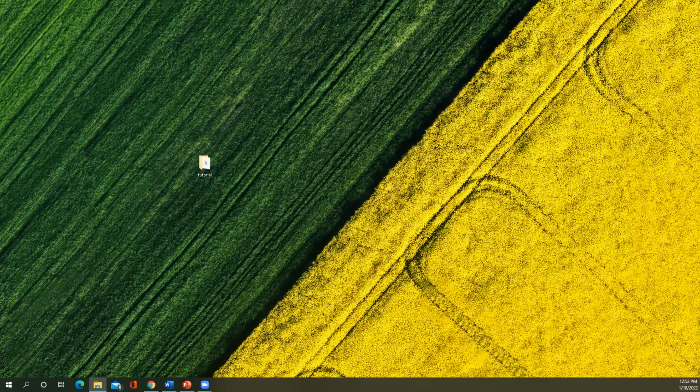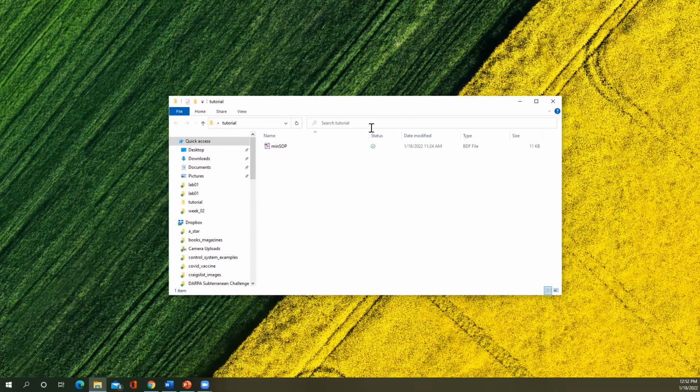Within that folder, when we open that up, I have a Quartus schematic, right? You'll want to do the same in your lab. I believe the schematic you're given is called circuit A. So you'll want to place that file within here, and then we'll see how to add it into the Quartus project. And so we need to create the Quartus project next, right?